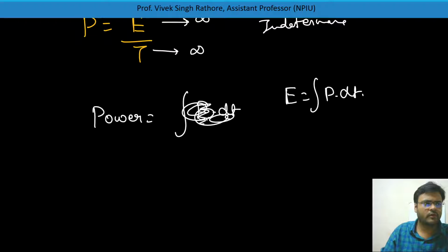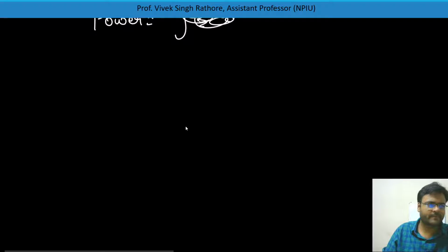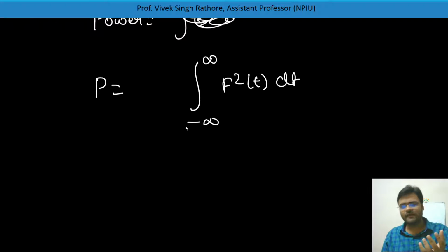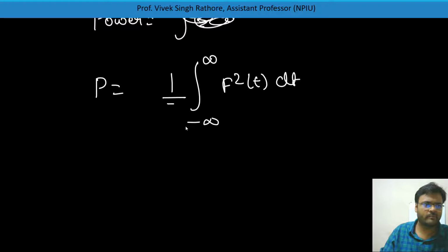So what we'll do, energy formula you already know, and 1 by T is there. So let's do it. Power will be equal to the integral from minus infinity to infinity of the energy term, f squared(t) dt. Earlier you used to know this, and we have to do 1 by time also for power, right? So 1 by time also will be for power, and for a finite value of power we need to take the limit T tending to infinity.